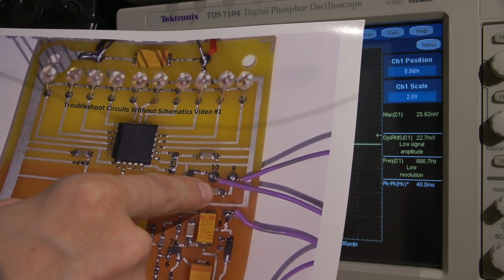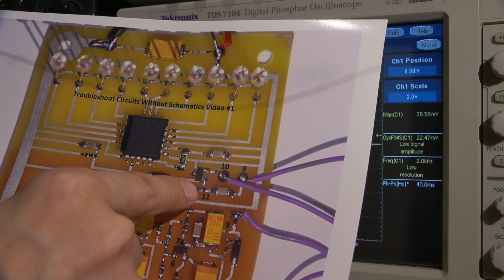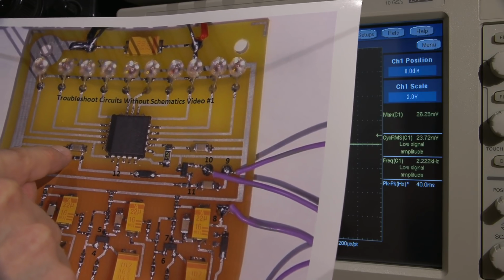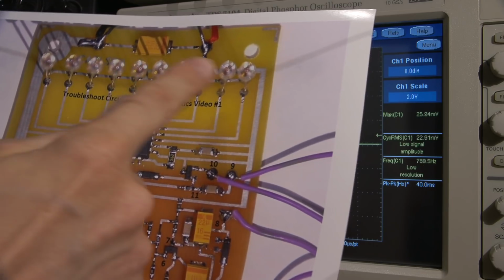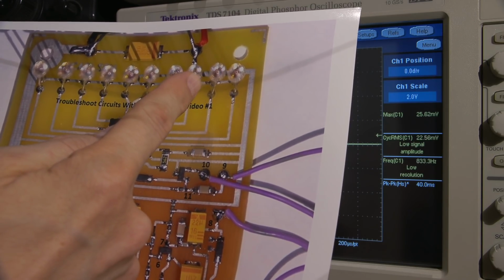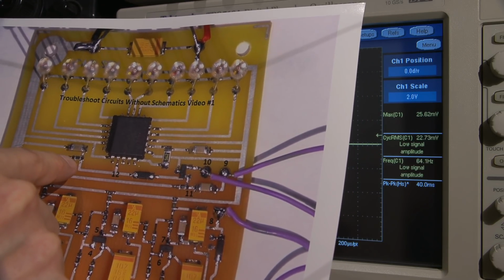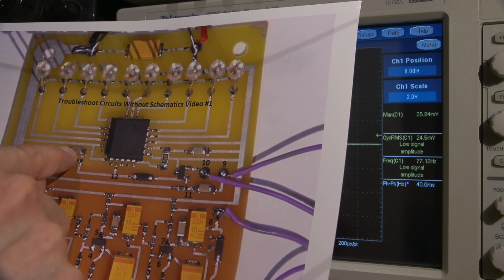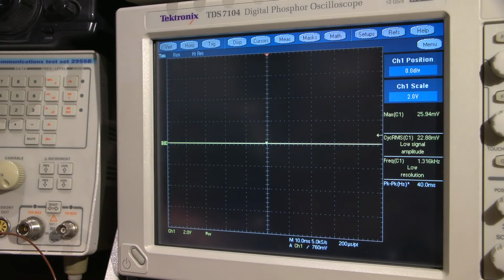So what we'll do is move to number 12 here, and we'll take a look at that DC level with the scope. Now, this component here could get tricky because this isn't designed to turn this directly into nice clean DC. If we wanted to do that, this display would take a long time to go up and a long time to come down again, because we'd need one heck of a resistor here and we'd need a lot of drive. So this is a balance point in the design. Down the road, I'm going to get into telling you how I figure out these balance points. All right, so again, we're just troubleshooting in this episode, so we'll keep this easy.